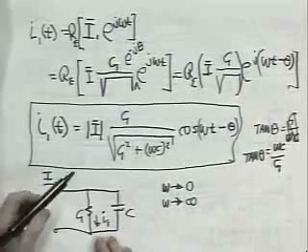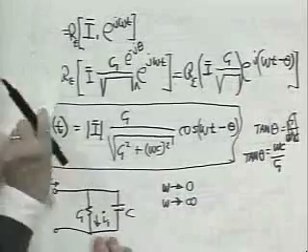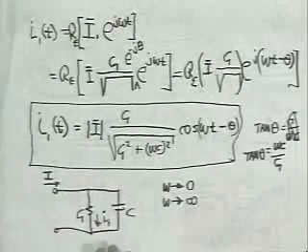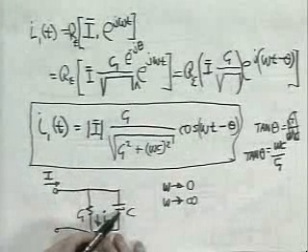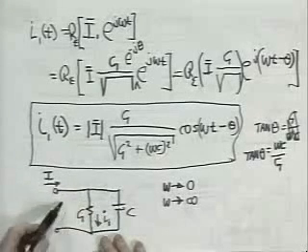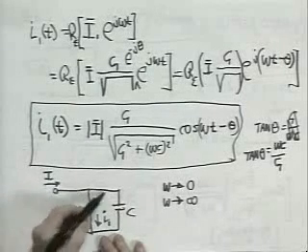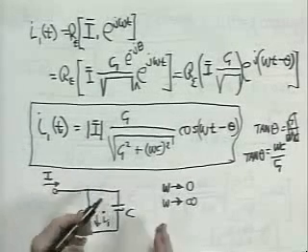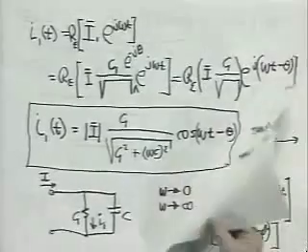Well, look at the circuit. Making omega larger and larger means making the admittance of the capacitor larger and larger. In a resistive analogy, it would be like making this conductance larger and larger, the resistance smaller and smaller. And in that case, you probably wouldn't hesitate to say that eventually all the current goes through the least resistive path. Well, in this two-element circuit involving an energy storage element, all the current at very high frequencies goes entirely through the capacitor. It has the largest admittance. It gets the lion's share of the current.